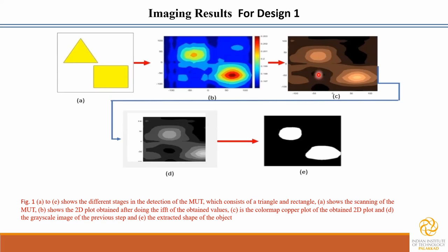Change the colored image to its equivalent grayscale image, so that by using various image processing algorithms, we can extract the object or metal from the original image. For the material under test image, global thresholding is used to segment the metallic part from the image. For the copper plate image, we use the Gaussian filter followed by image growing, which is used to segment the copper part from the image. For the concealed object image, the Gaussian filter is the best.